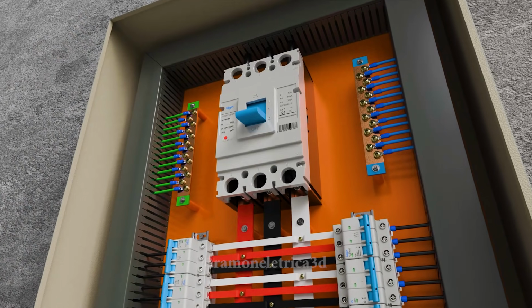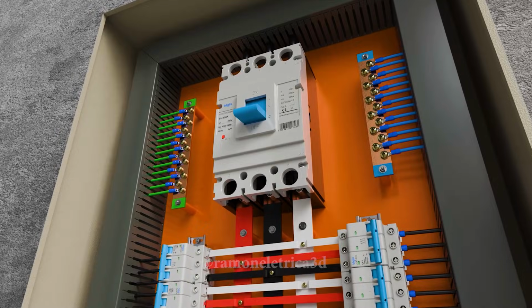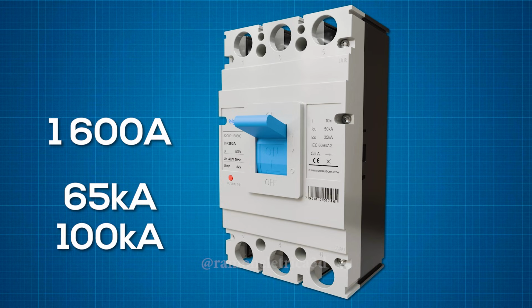Molded case circuit breakers, MCCBs, are used in industrial installations and have rated currents that can reach up to 1,600 amps, with short circuit capacities ranging from 65 kiloamps to 100 kiloamps, meaning 65,000 or even 100,000 amperes.